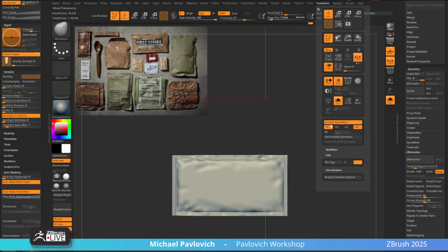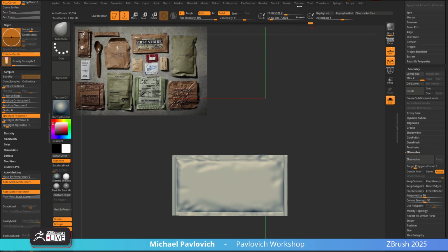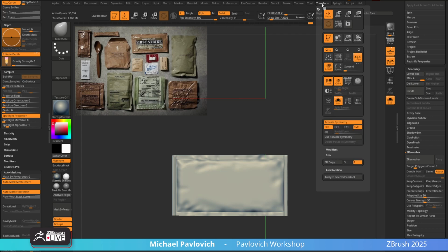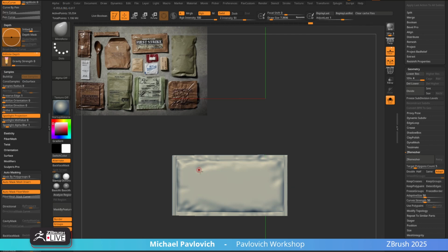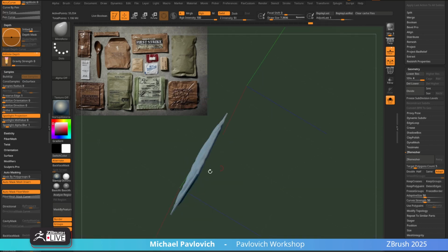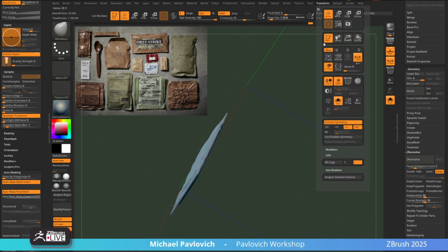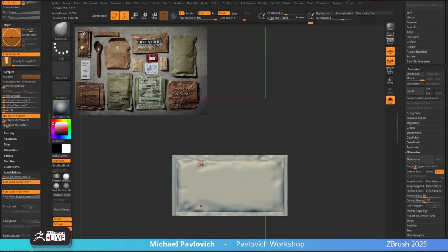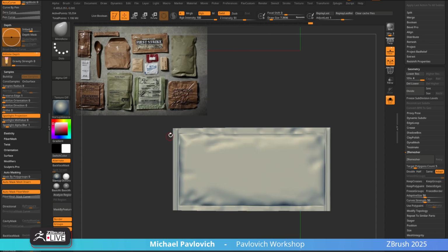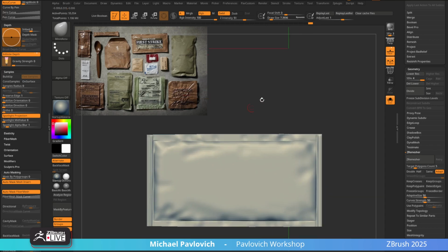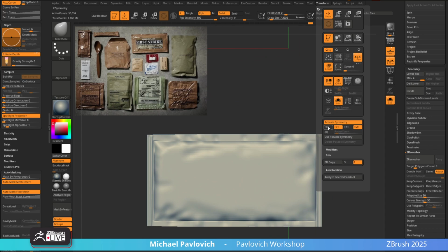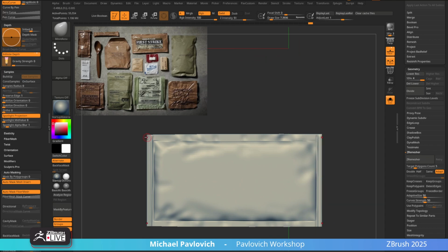Now we can go in here to transform, and right now it's across the X-axis. Let's switch that to Z. So now, Z is front and back in this case, which isn't terrible. Y, that's what I'm looking for. So now I can go through here and, in fact, let me see, let's do X. This isn't perfectly symmetrical, but it might actually work. Let's give it a shot.